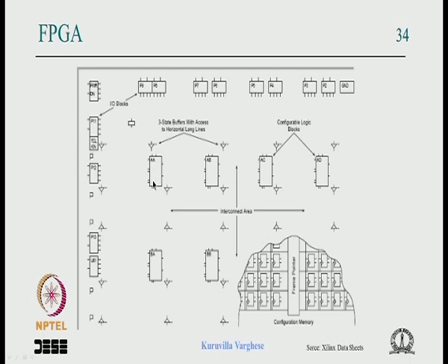Maybe we will do very wide computation, like we get 32-bit data, we might choose to convert it into 64-bit data or 128-bit data and do it in parallel, at a much higher data width, to achieve performance. So though FPGA lacks in raw clocking speed, maybe an ASIC will clock at say 1 gig or 2 gig, maybe FPGA will clock only at say 200 megahertz or 400 megahertz at the most when a design of reasonable complexity is put into it. But by design techniques, by doing wide data computation, multiple cores and so on, you can replicate the number of computational units, do a lot of parallel computation and achieve performance maybe much bigger than the ASIC.